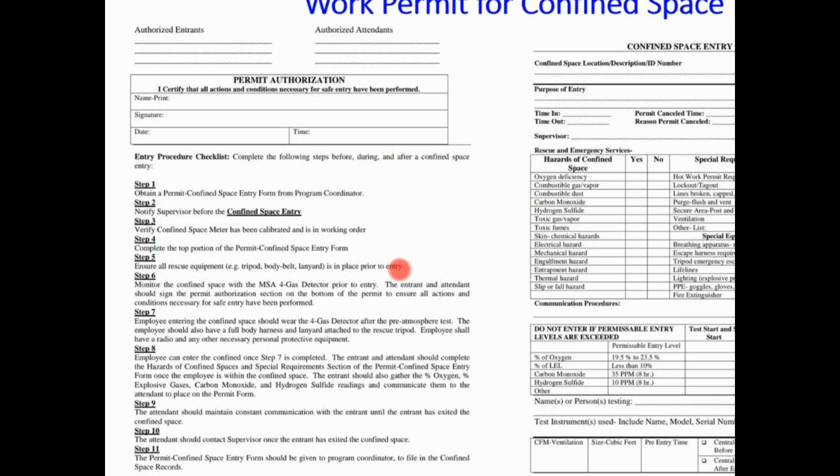There should be an emergency team or a rescue team present in the work area where you are going to perform the work. That may be a tunnel, a pipeline, an underground working area, a storage tank, etc. At that place, the emergency or rescue team should be there. If you are working in an area where no ladder is available, then we have to use a tripod stand, and with the help of wires, ropes, safety harness, hard hats, and helmet systems, we have to follow the instructions from that rescue team.